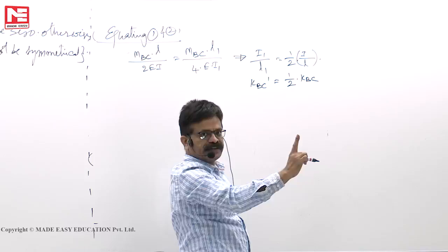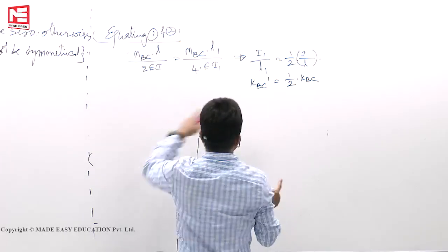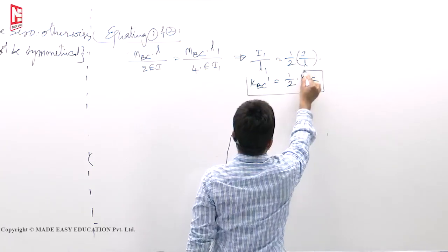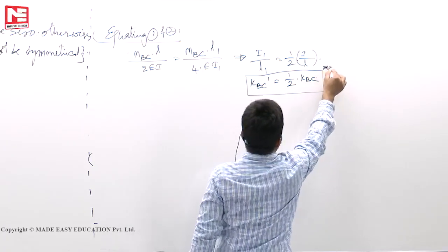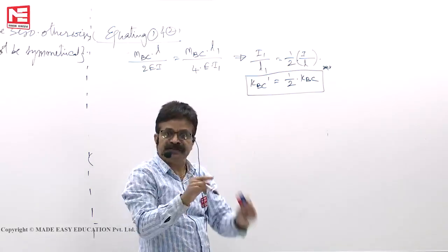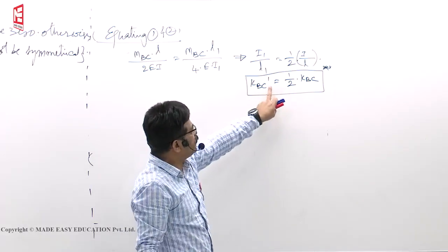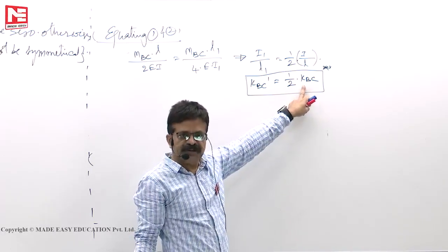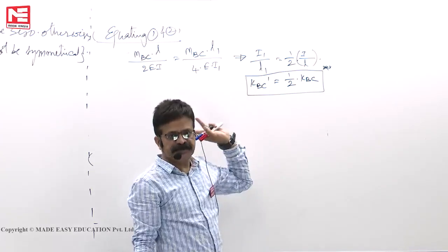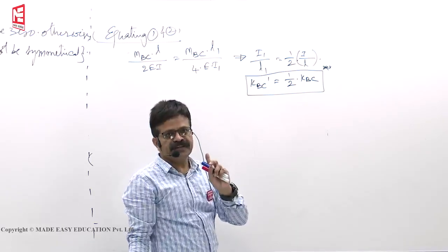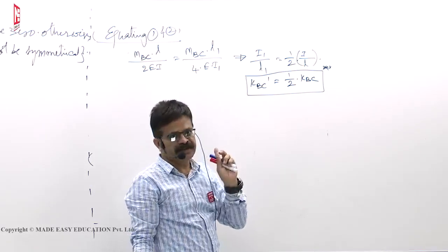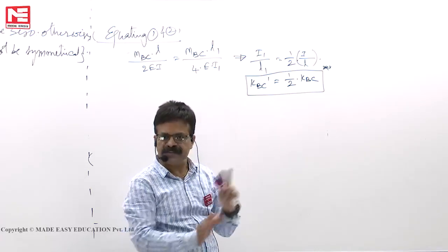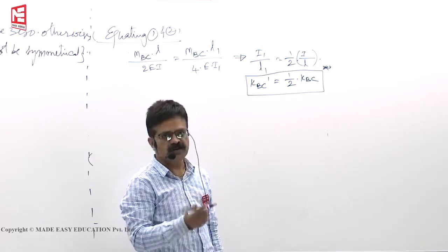Because of the continuity of the beam, moment is also developed, meaning it is like a rigid joint behavior. So half of I by L we have taken. When you are dealing with the end moments only, I can take a beam whose stiffness is half of the original beam, then slopes and moments are the same. Deflection profiles will match only when you are applying the end moments. Equivalence is valid only when you are dealing with the end moments and no other applied loads.